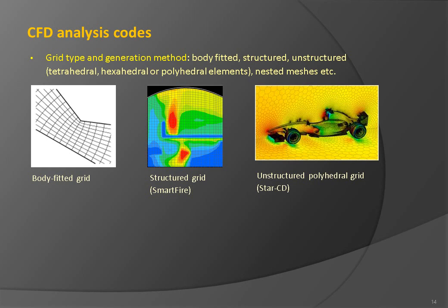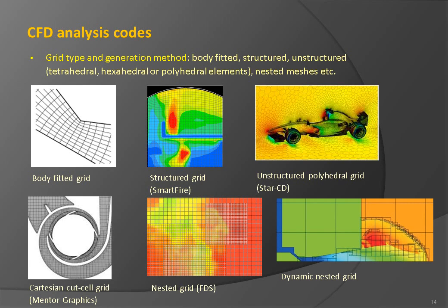They can be recognized by their Cartesian elements, sometimes in their body-fitted forms, whereas the unstructured grids may consist of hexahedral, tetrahedral, prismatic, or even polyhedral elements. Different hybrid variations can also be found. More recently, a group of grid overlapping methods appeared.